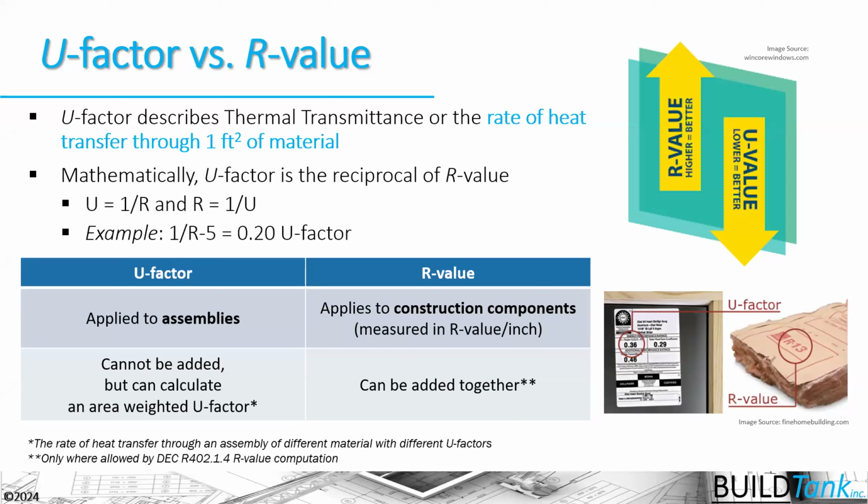And that's really one of the big reasons why we always use U factors to describe windows, because we're not describing the center of glass R value. We're describing the entire assembly of that window's ability to resist conduction from, again, inside to outside or outside to inside, from higher concentrations to lower concentrations.